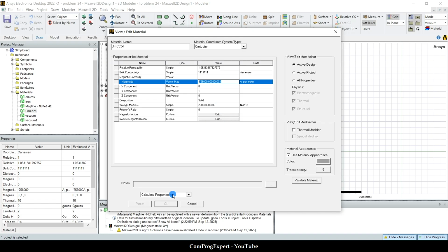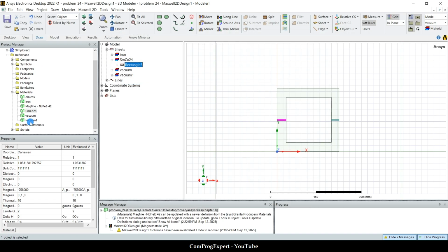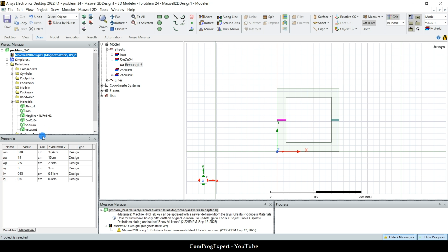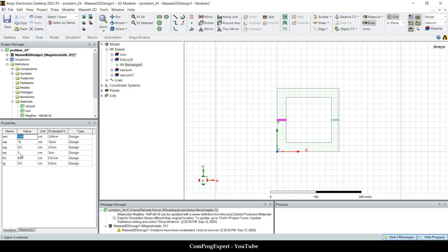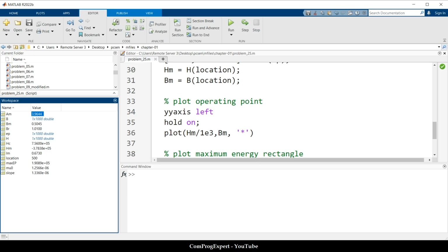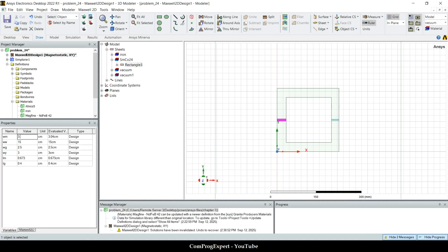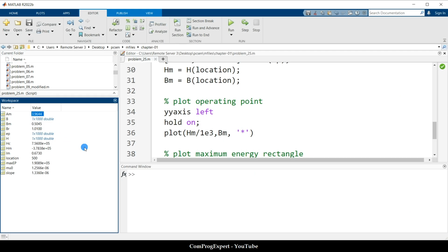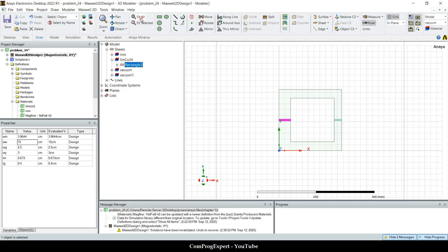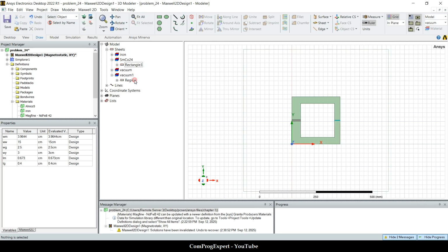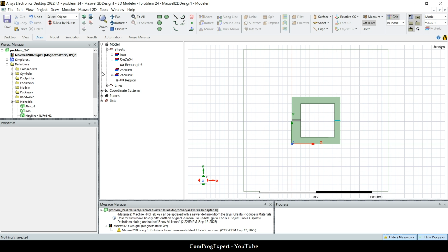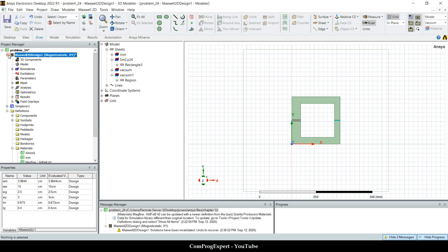So let's adjust these two numbers and repeat the simulation. Here, the length of the magnet is 0.673. The width of the magnet is 3.9644. This number. And yes, we can repeat the simulation. This is vacuum 1 again, neglecting leakage flux.